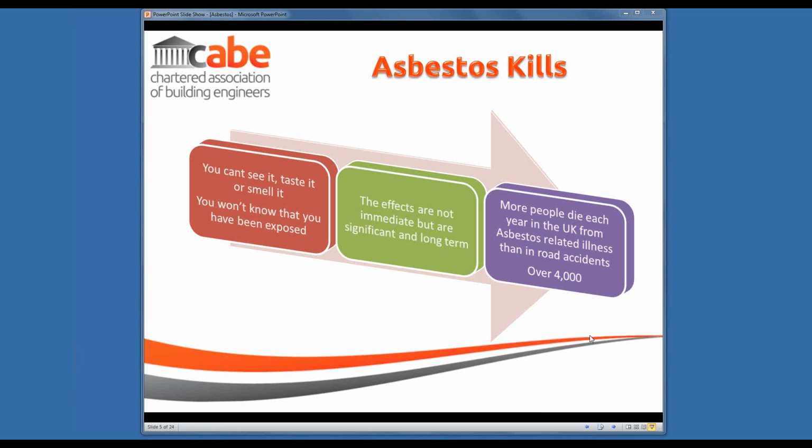So normally in most of our buildings, asbestos has been mixed in with something else, for example, the board and insulation coating. It can often look very similar to other materials. Since asbestos was being phased out and other alternative products were being brought in, it can be very difficult to know the difference between the alternative replacement and the original asbestos, particularly when the time of installation would allow for work still to have been using asbestos, or on the cusp of when we moved away from it. So anything built in the 1980s, 1990s, it would be difficult to know for sure whether it's an asbestos product or something that's replaced it later.